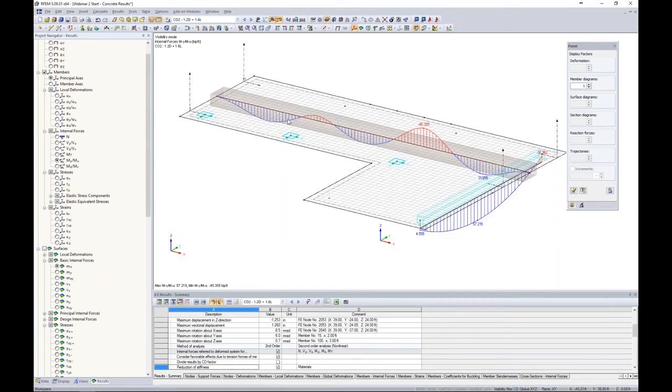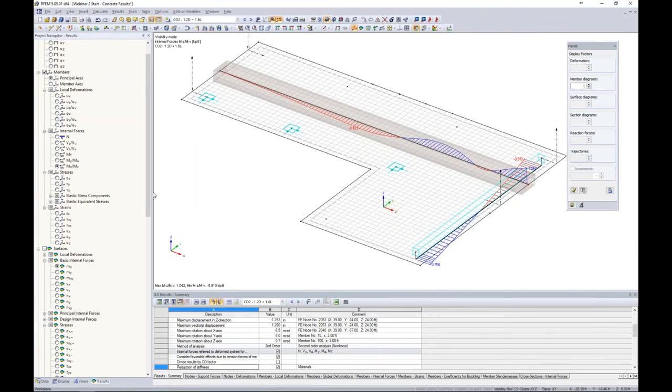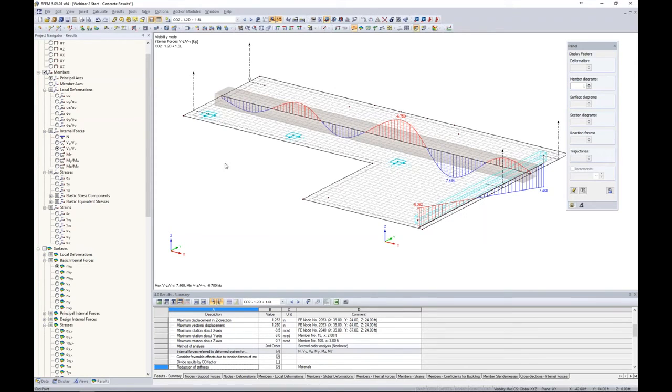So that can impact the way that you're viewing your results. You want to make sure and increase those numbers of sections here if you see any type of discontinuities that we saw with the beam before. So now we can see that our moment diagram is displayed quite nicely here for our strong axis. Remember, these are the internal forces for our 4-foot wide section, that we can take these internal forces and go and do our own design. We can take a look at the weak axis bending here. We can even take a look at axial and shear forces. These are all relevant within this particular section. But this is what I'm saying when you want to take a look at the internal forces of our moments, that the centroid of our elements that we're interested in must be at the same location as our result beam's axes. So just something to keep in mind there.